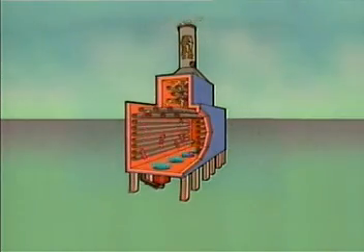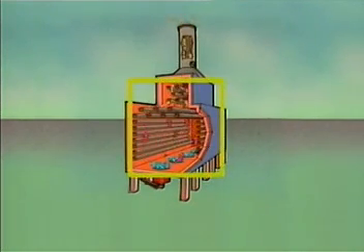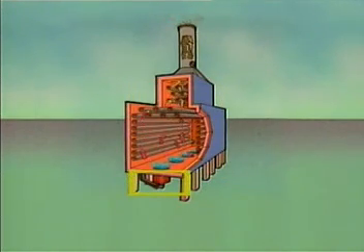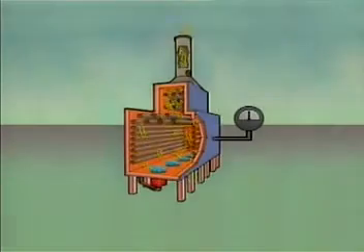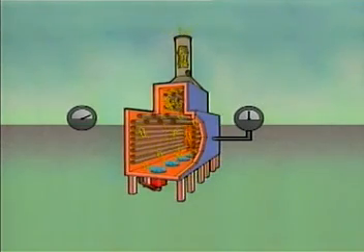In a natural draft furnace, the hot combustion gases, which are lighter than the outside air, rise up the stack and create a lower pressure in the furnace. As this occurs, cooler, heavier air from outside the furnace is drawn into the burners through the air registers. Airflow through a furnace is produced by a difference in pressure. In an operating natural draft furnace, the pressure inside the furnace is less than the atmospheric pressure outside.